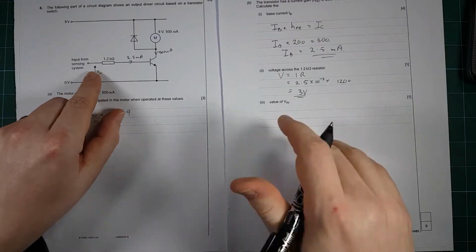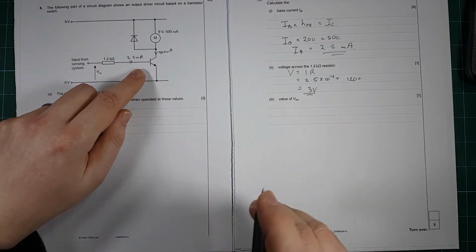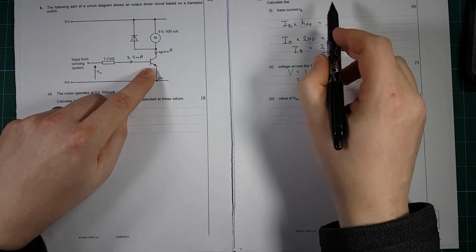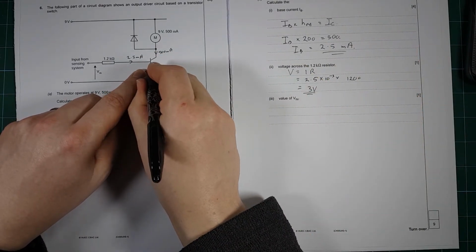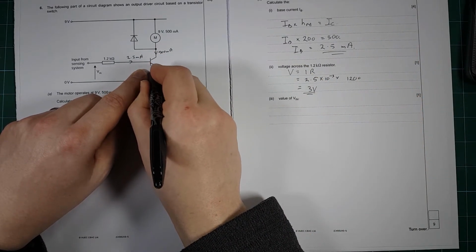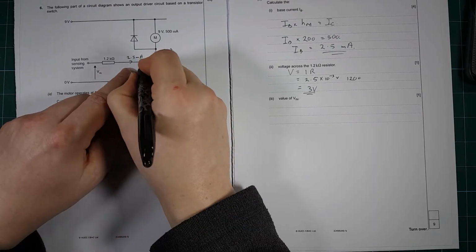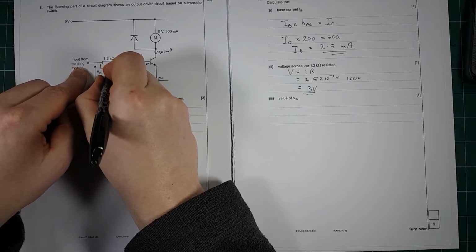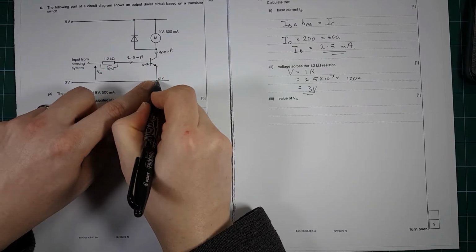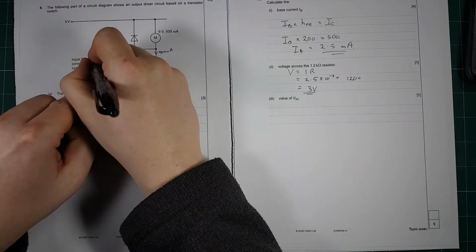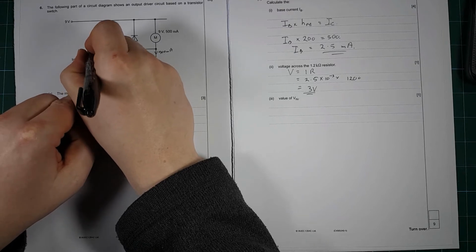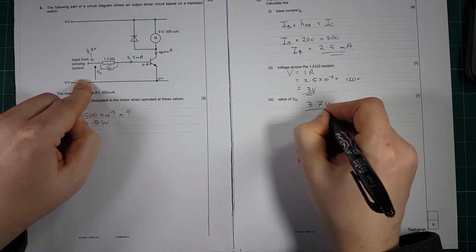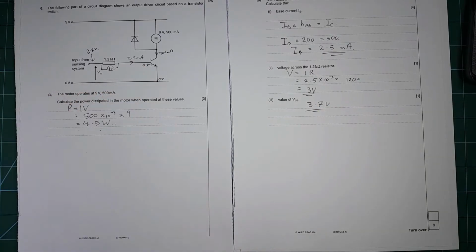So the value of VN, right, so we start here at 0 volts. The transistor is saturated, it's on, so that means there's a voltage drop across this. This is like a diode drop, an NP junction, so this will be 0.7 volts. There's 3 volts across here, which means that we've got 0 plus 0.7 plus 3 volts. So this point here will be 3.7 volts. Got to remember to add in the base voltage there.